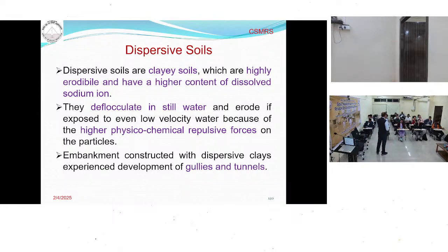But what is happening there? These soils have a high content of sodium. In normal clay soils, the net force among the particles is an attractive force. But due to the high percentage of sodium, here the net force among the soil particles is repulsion.